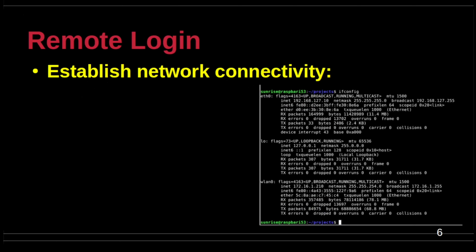After the boot is complete, the first essential task is to ensure internet connectivity through Wi-Fi or Ethernet interfaces. If the board is not enclosed in a metallic case, then an external Wi-Fi antenna will not be required. Use the ifconfig command to establish the availability of the interfaces.